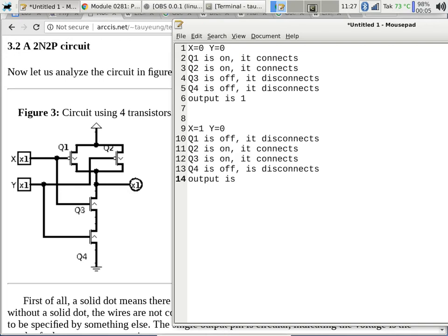Okay, so it depends on whether you have safety features, right? If you have the proper fuse boxes or the jumper boxes, that fuse is going to blow, or the jumper is going to kick, so it will disconnect because it's going to exceed the 20 amp, the 30 amp, or whatever that jumper or the fuse is rated at. What if it's not connected through a fuse to the supply? Then it gets very hot, and it will melt itself until it disconnects.